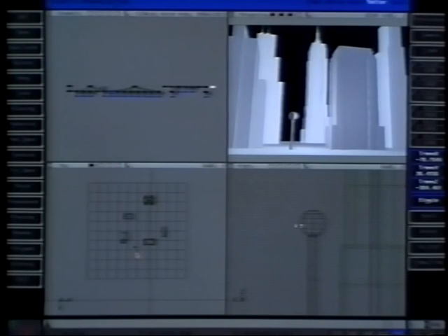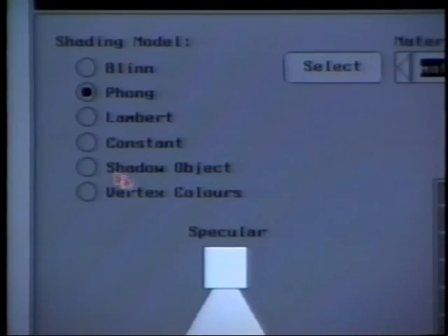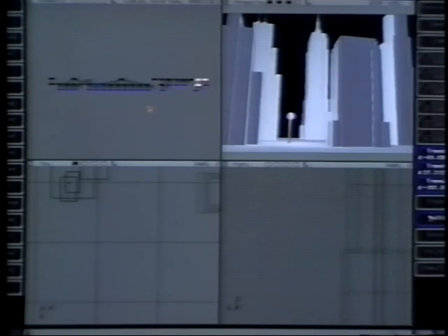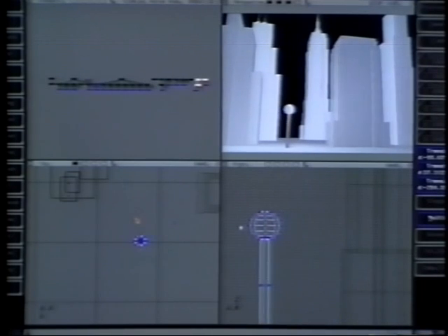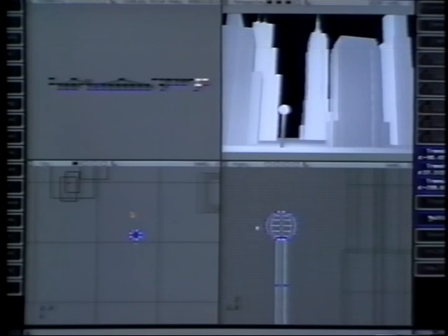This sample scene still has global ambience turned on. If we want this lamppost to look like a light source, we can position a point light near it, and we can give the globe at the top a constant material. Now moving the light and lamppost together lets us add shading to the buildings. But if we wanted to map illuminated windows onto a building, we wouldn't want to make the building constant like the globe, because the walls should still be getting this illumination from the lamppost.